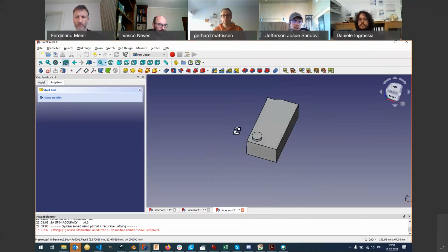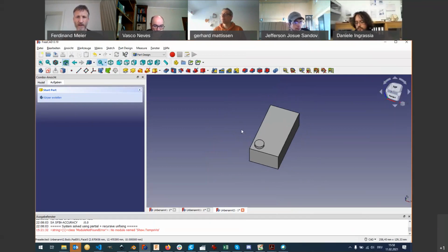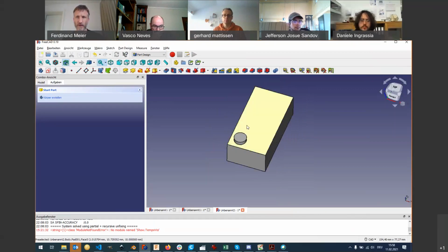If you middle click and then left click just shortly, you also enter a zoom mode. So there are several ways of zooming, either with the mouse wheel or middle and left clicking shortly. And left click and shift also works. For me it doesn't work, but control and right click is also useful.